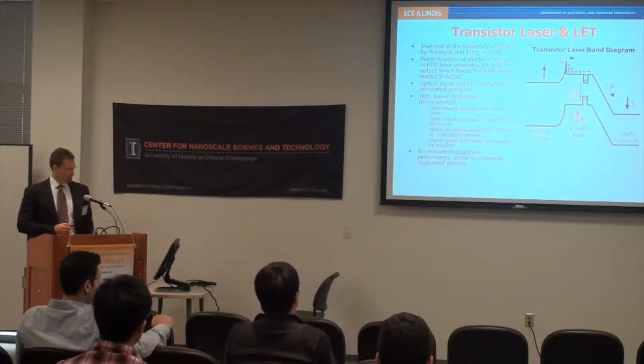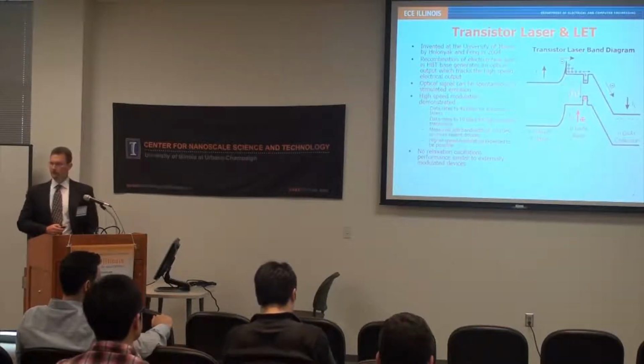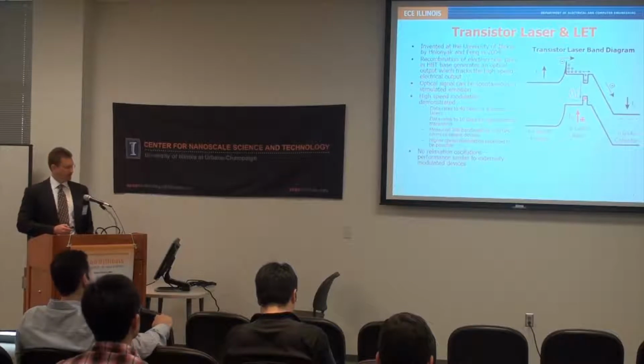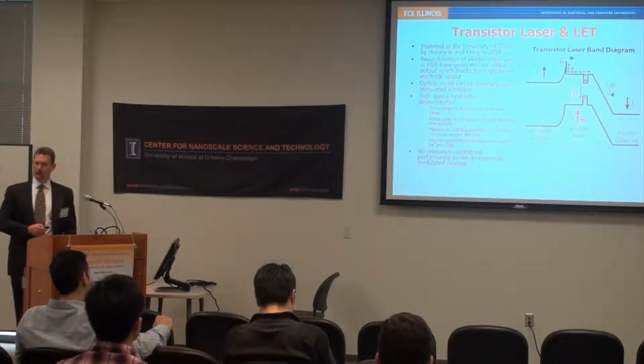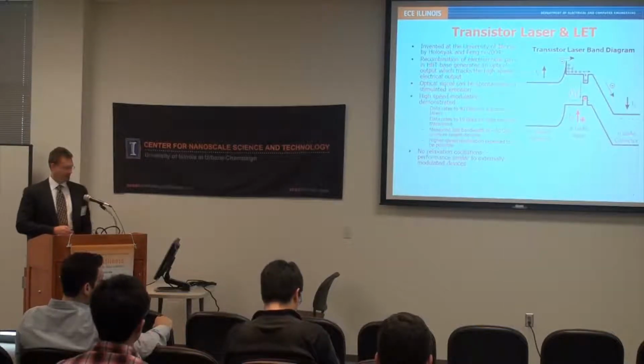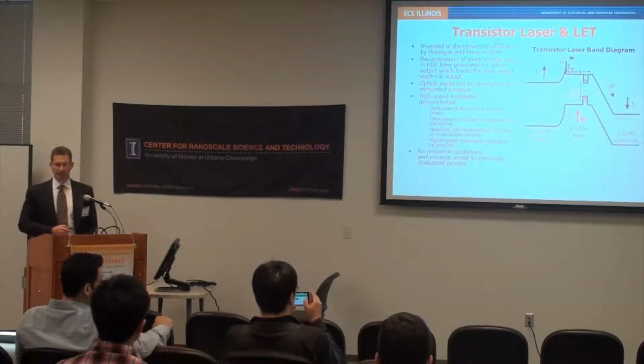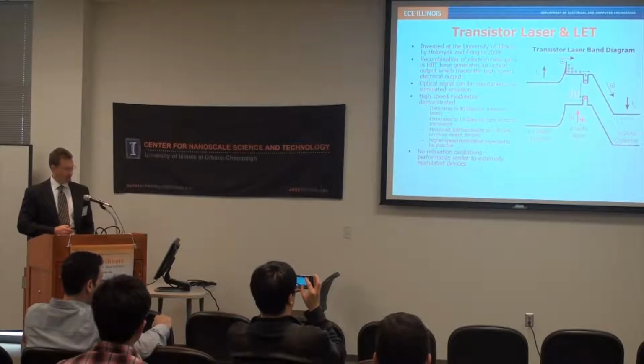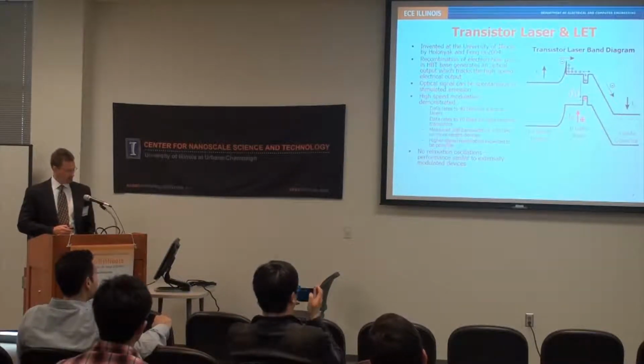So what they did was make a modification to a traditional HBT structure. They added a quantum well into the base region, which allowed somewhat more efficient collection of the fast recombining electron-hole pairs. The slow recombining electrons effectively get swept out in the reverse-biased base-collector junction of the device.